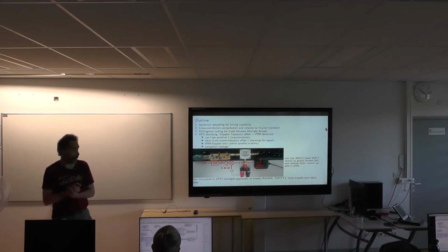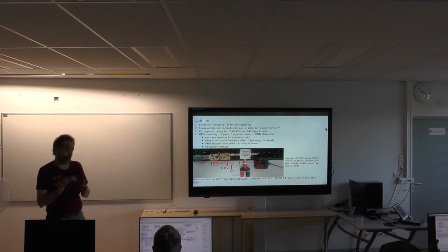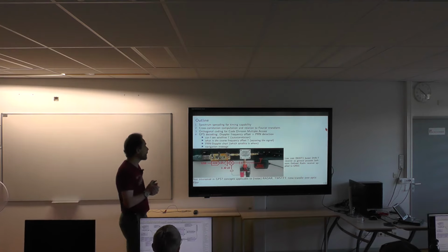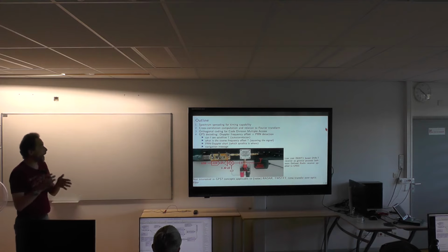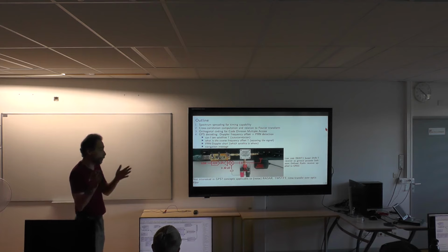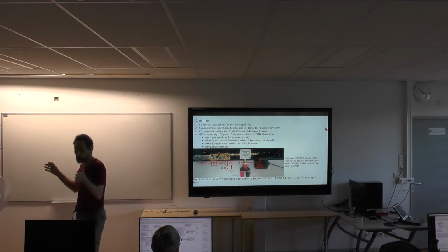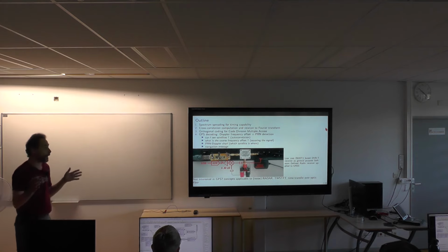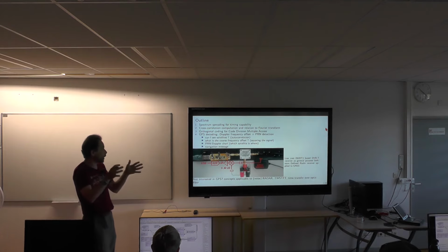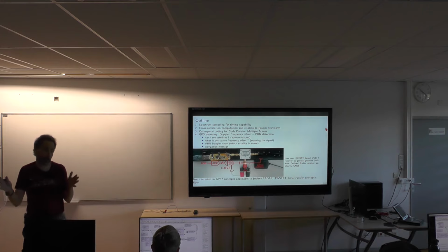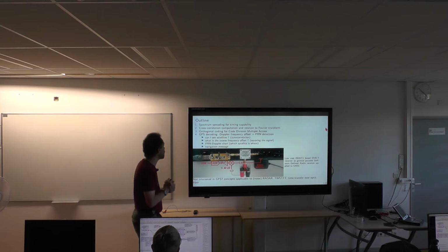We're going to see, once I've said that we need to spread the spectrum for time transfer, how we identify the pattern that has been transferred, and we're going to see that this is done through the cross-correlation estimator, and how we compute this cross-correlation in the Fourier domain. We're going to see how all these satellites are broadcasting at the same frequency, and yet we can identify the message broadcast by each satellite, and that's called code division multiple access, because each payload broadcast by each satellite is actually encapsulated in a unique code, and we're going to see how to do this.